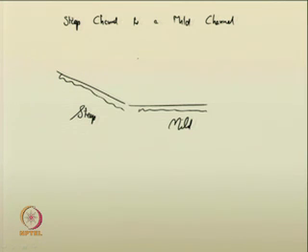So, you have to see that the slope of the water surface profile can be positive only in zone 1 and zone 3, it has to be negative always in zone 2. So, keeping all those criteria, what are the profiles you can imagine? You just do it as homework. More discussion on this aspect will be in the next module actually. So, we will see that.